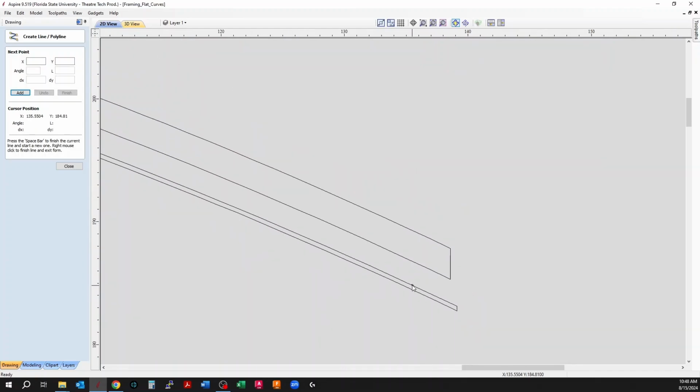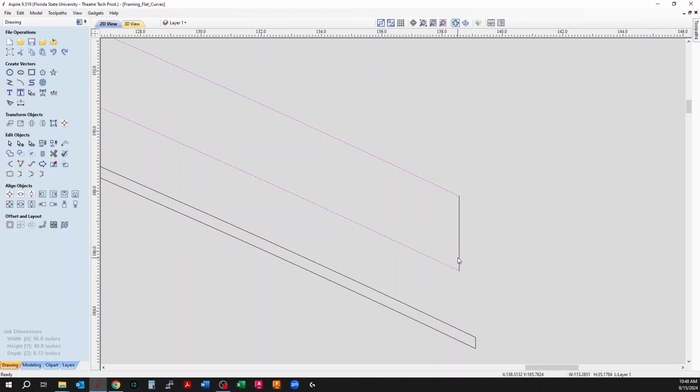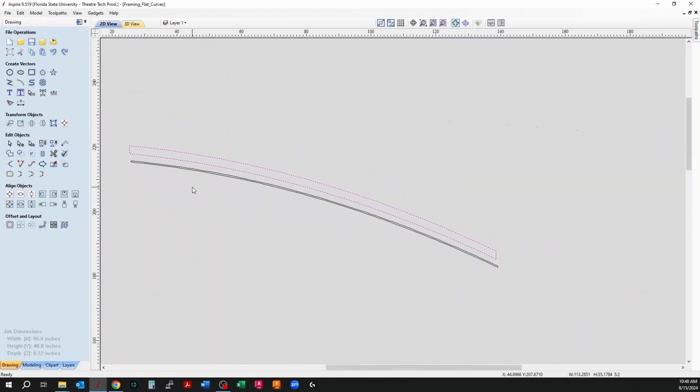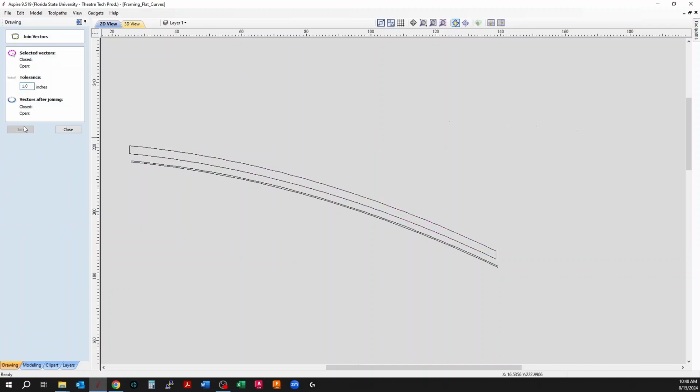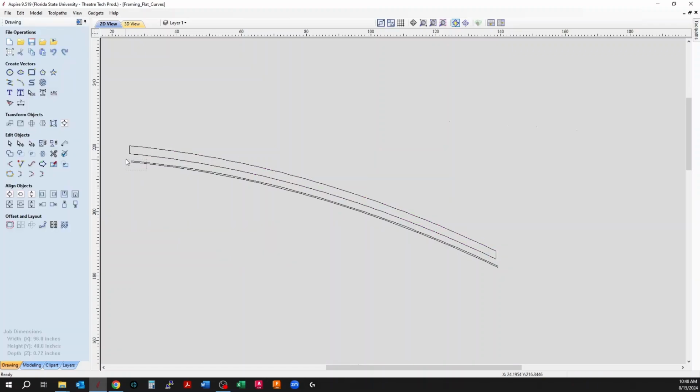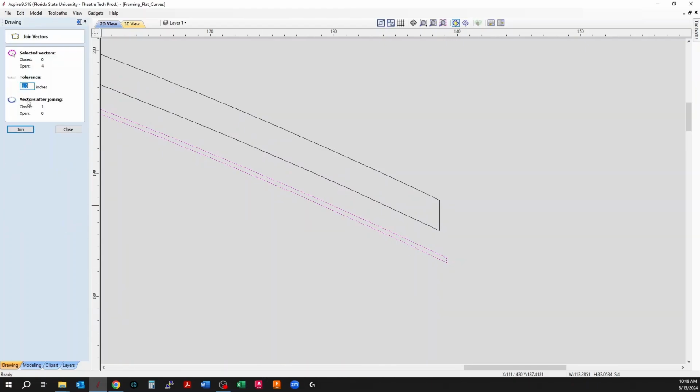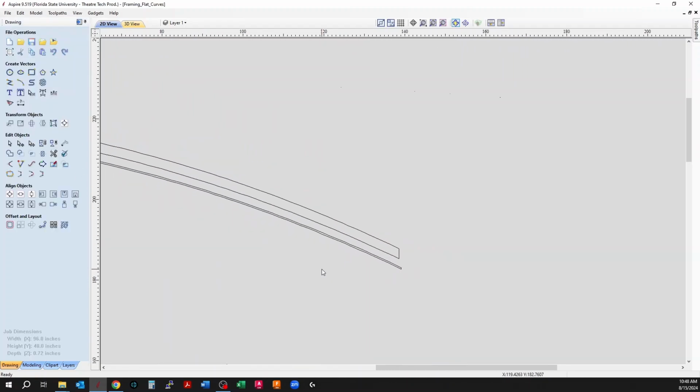And then there's that. Now you want to make sure that these shapes are closed, because right now they're all individual lines, right? So I've got that. It's got the end. It's already closed. I'm going to close that open one to a closed one, and I'm going to close up this shape as well. So just make sure all that stuff's selected. 4 open to 1 closed. There it is. So that's all joined together.